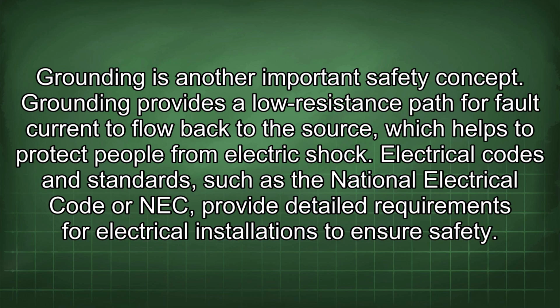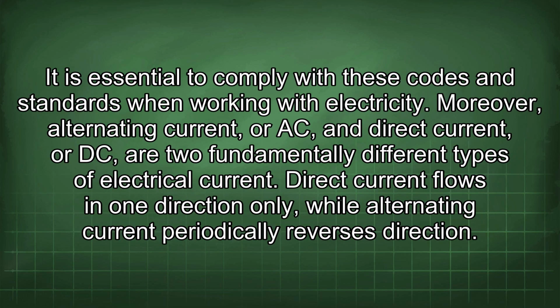Grounding provides a low resistance path for fault current to flow back to the source, which helps to protect people from electric shock. Electrical codes and standards, such as the National Electrical Code or NEC, provide detailed requirements for electrical installations to ensure safety. It is essential to comply with these codes and standards when working with electricity.